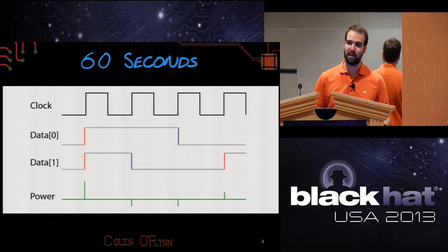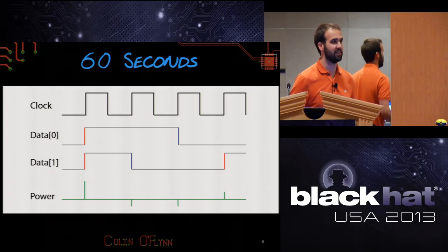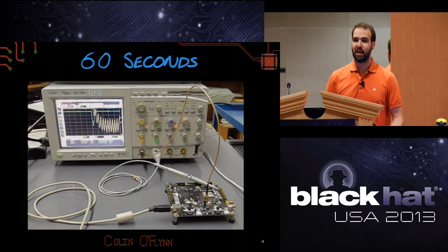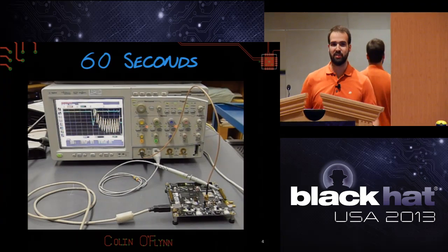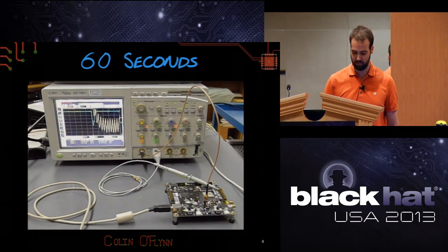And we can look at the power that device is consuming on a very short time scale, clock cycle by clock cycle, to figure out some information about the data that it's processing. Once we figure that out, we can actually break the encryption, that is, figure out what the secret key was or some other secret that we're not supposed to know.